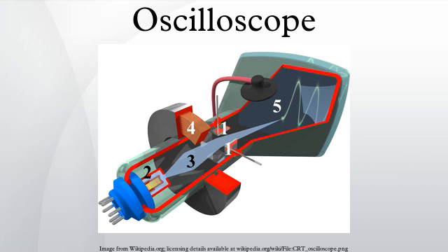There are special high-voltage probes which also form compensated attenuators with the oscilloscope input. The probe body is physically large, and some require partly filling a canister surrounding the series resistor with volatile liquid fluorocarbon to displace air. At the oscilloscope end is a box with several waveform trimming adjustments. For safety, a barrier disc keeps one's fingers distant from the point being examined. Maximum voltage is in the low tens of kilovolts. As the voltage continues to climb, another tiny arc charges the tip further.